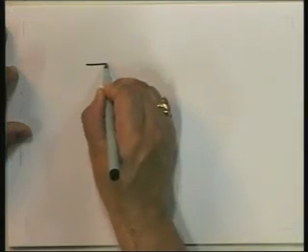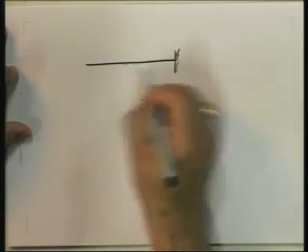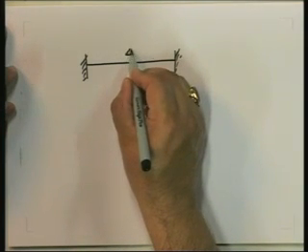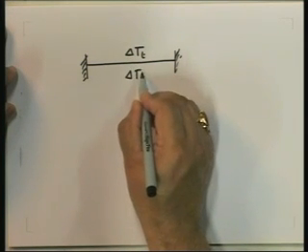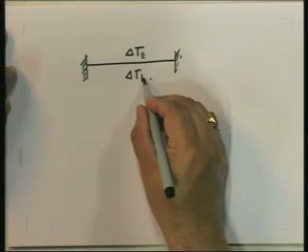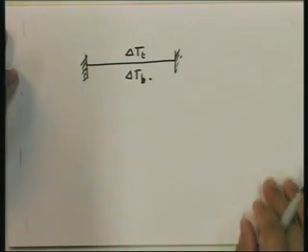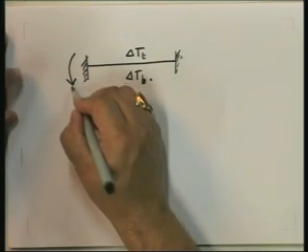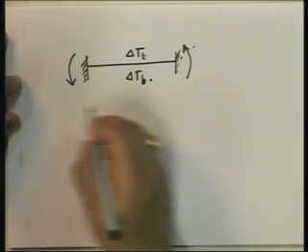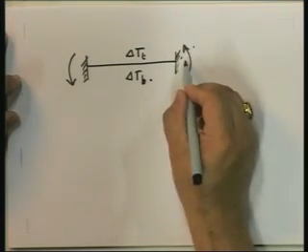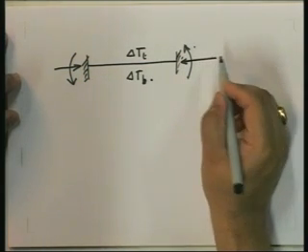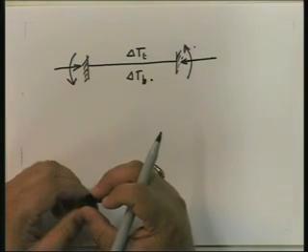Okay, what does that mean? But then you see, our basic member that we have is this. Then I'll talk about the modified member a little bit later. This, and here we have delta T top and delta T bottom. Now, how do I compute the fixed end moments, as well as in this particular case, if there's an extension, you also have these forces that come into picture.